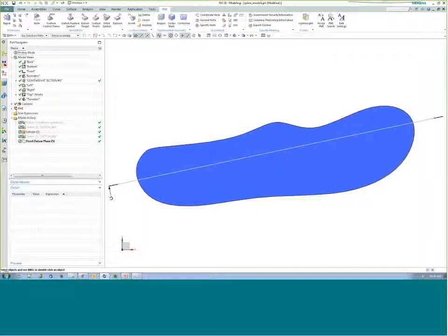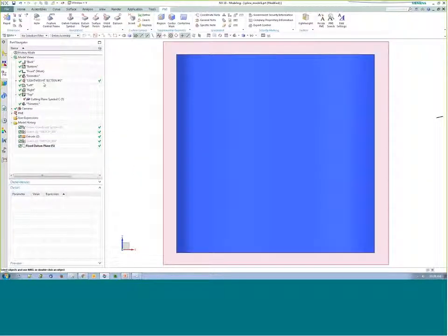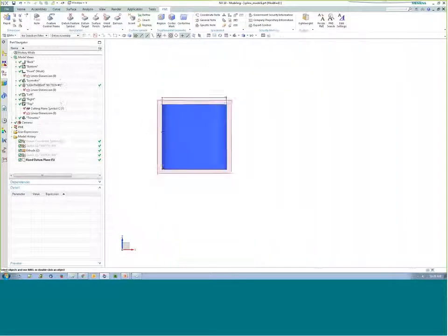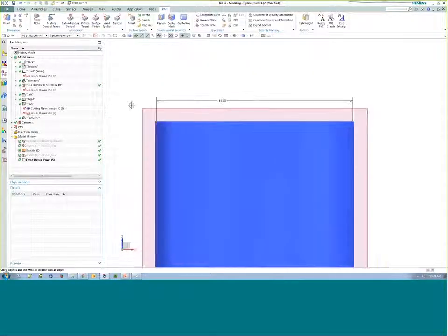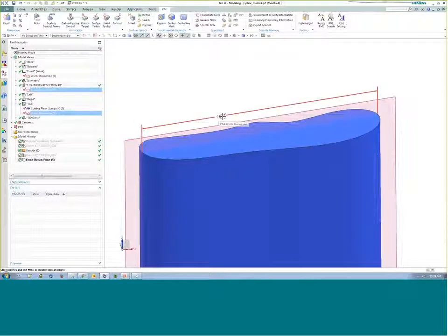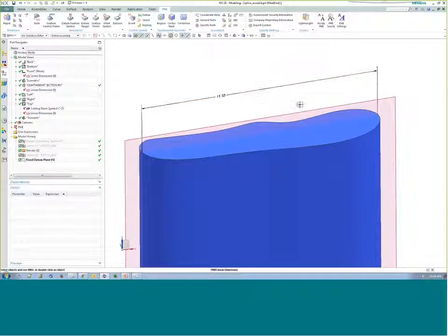And now, when I go into any other view, I can display that PMI in that view. Even though I couldn't really create the PMI in that view without the lightweight section, that PMI element or dimension is visible or available in any of the other views.